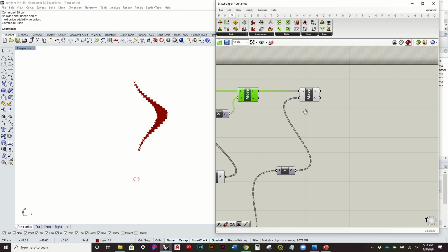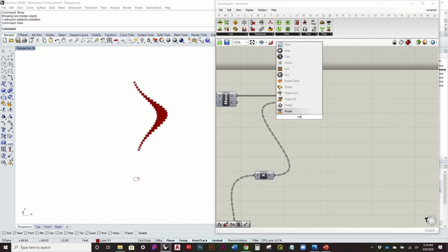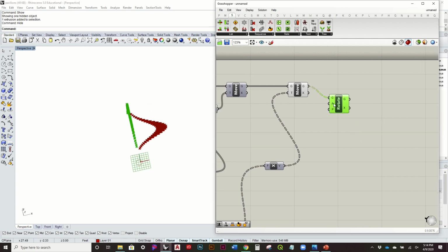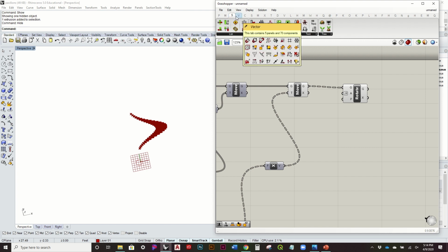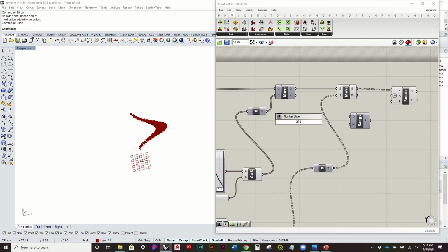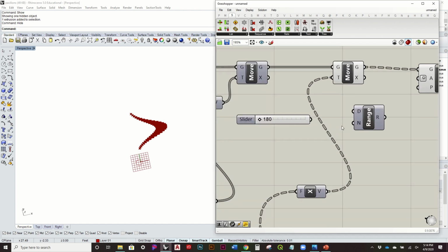So I'll go ahead and turn this off. And now I want to rotate these points. So I want to make sure I can obviously use that same plane. It doesn't really matter where it's at, but I do want to change this degrees. And I do want to, again, create a range of values between 0 and around 350. So I'm going to use range. I'm going to go again from 0 to 350, and I'll try to do something like 180 less than 350. So that way I don't go too much further off.